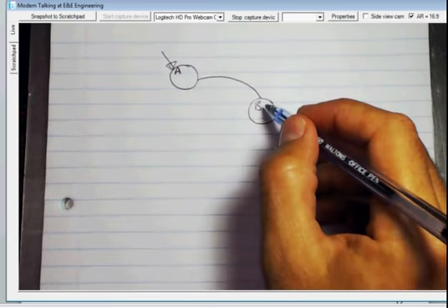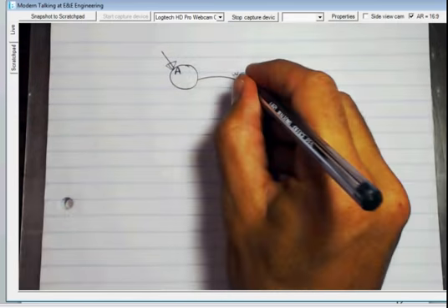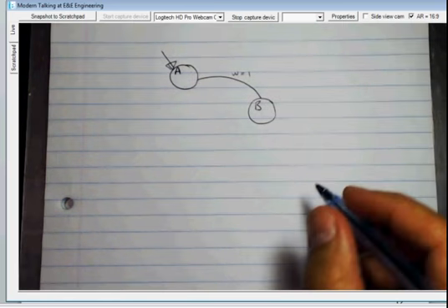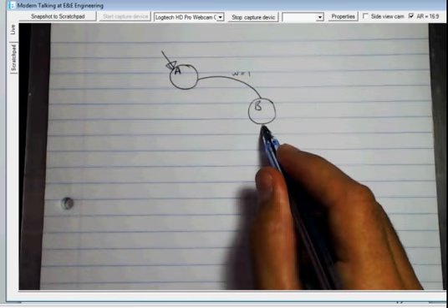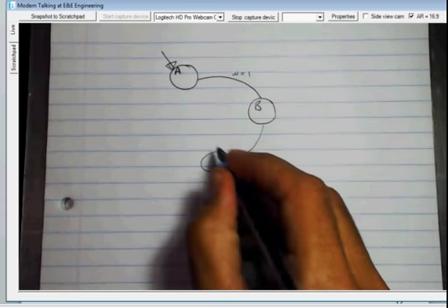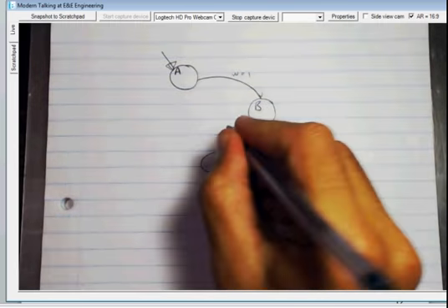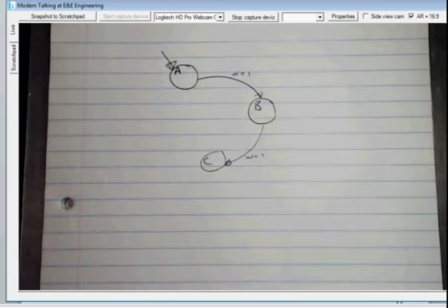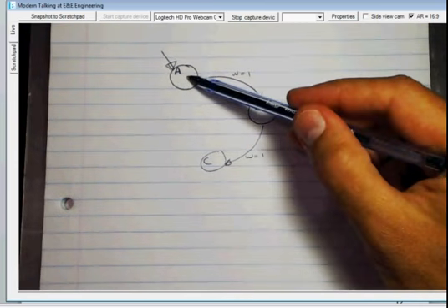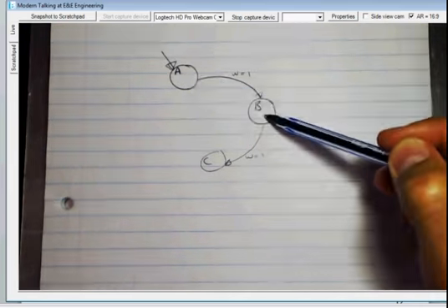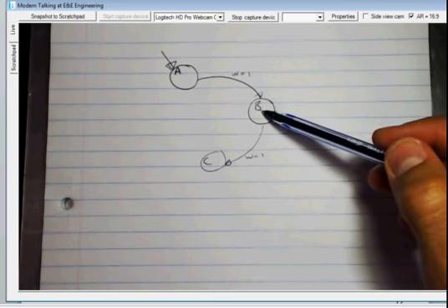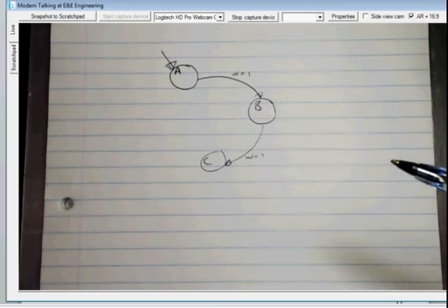State B is we've received a 1, or there was a 1 at the input. State C is we've received yet another 1. So in this case we've received another 1. We transition into what I've called state C. So I've received nothing, I've seen 1 at the input, and then I've seen 1 at the input as well.